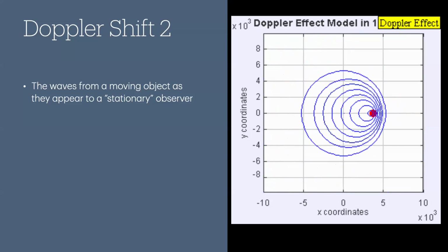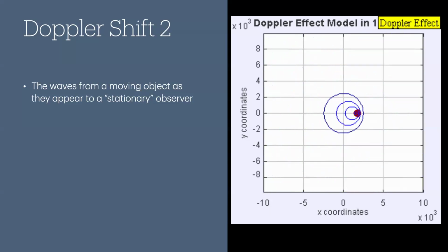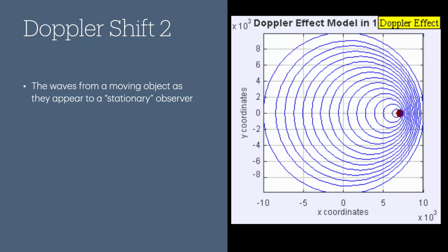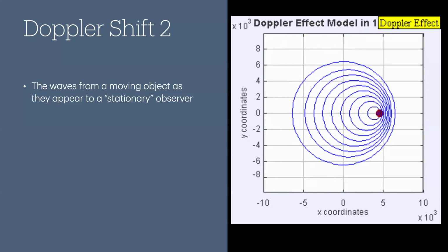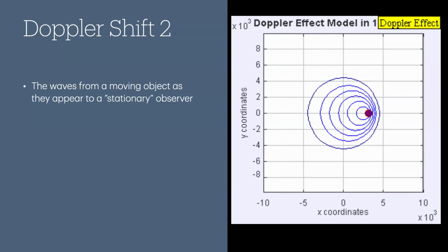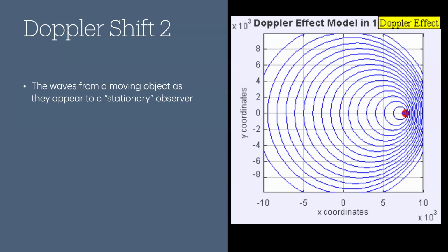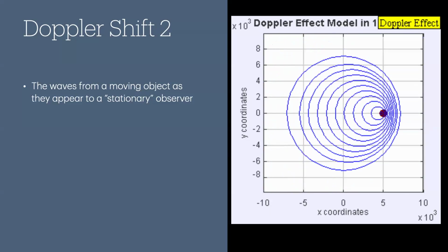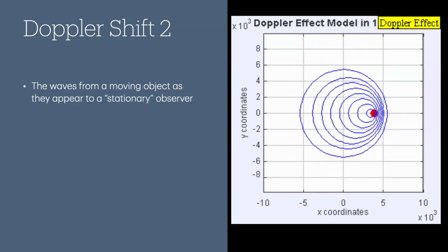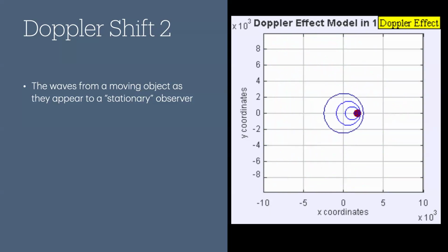So the apparent frequency we see as it approaches us is much higher than the actual frequency it's transmitting at. And in recession, if you look at it from behind, we see a much lower frequency by exactly the same amount. Okay? And we have to compensate for that in real time as we talk to the spacecraft. So we compensate for the Doppler shift. This is all done in the computer.